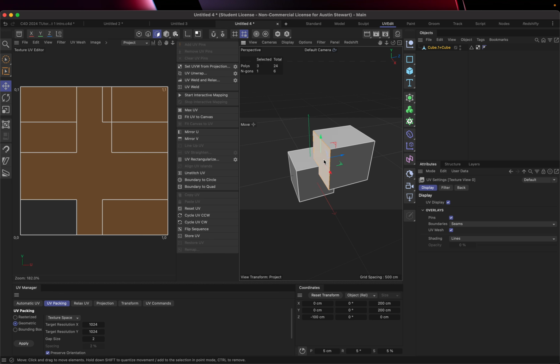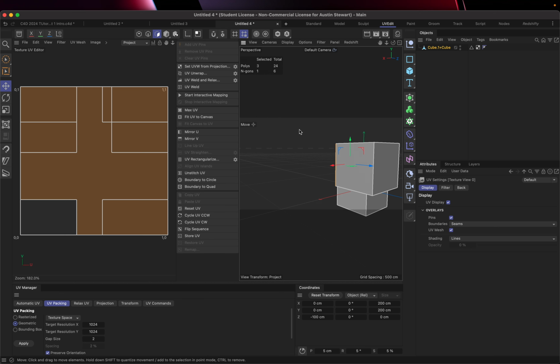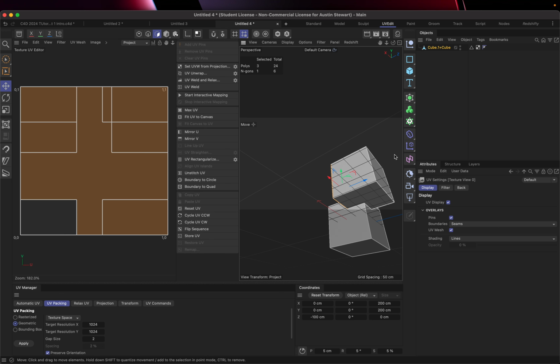So if I was to start here on this cube and come around, let's say I want this to fold up. I'd want to cut that edge, and cut that bottom edge, so this will fold up flat. And then let's say I want these to be like the wings or the arms of the cross. Well, I definitely would want to make a cut here and here, along with the one that's there. But then this would be a hinge, so it would fold flat. Same on the other side. And if I work my way around, these would be cuts, but I'd want this to be a hinge, and this to be a hinge. And then there'd be cuts down here as well.